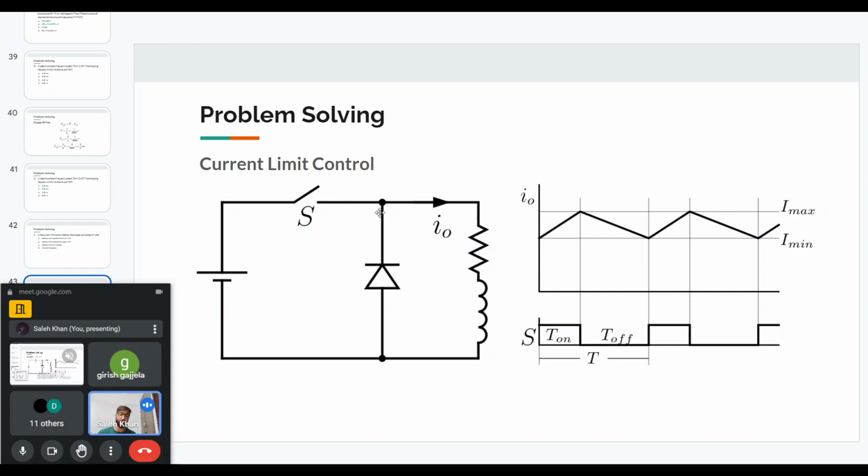In case if we had that case, then we can use the inductor volt second balance. But in this case, you will have to use the differential equation. You can find the expression for the load current, and the resistor voltage is quite simple. The inductor voltage will be just the derivative of that inductor current.